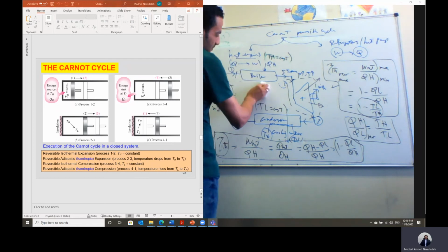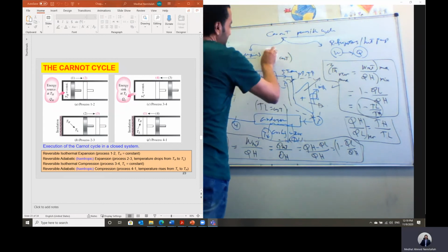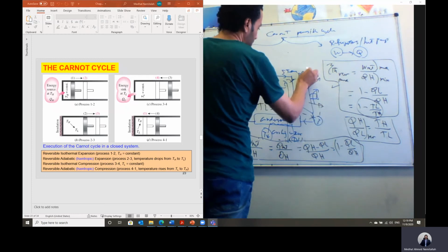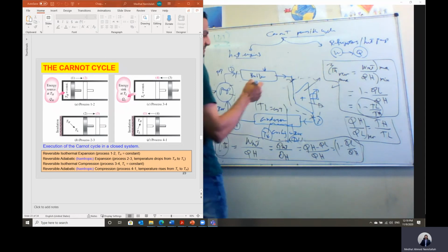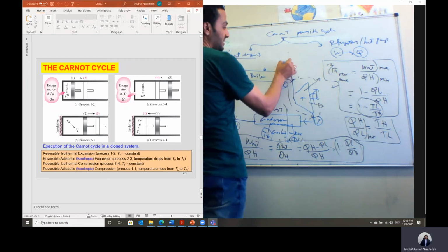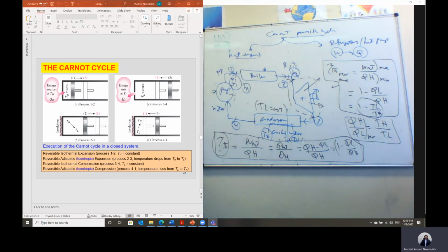So in some cases, they will not give you the value of the heat added or heat rejected directly, and they may not give you the work of the turbine as well. So what should we do in this case? In some applications, let's say this is step number 2, they may give you a steam power plant. They can give you the pressure P1 and temperature T1 at the inlet, then we can calculate the enthalpy H1. And at the outlet of this boiler, they give pressure P2 and temperature T2. Then using a steam table, I can calculate the enthalpy H2.